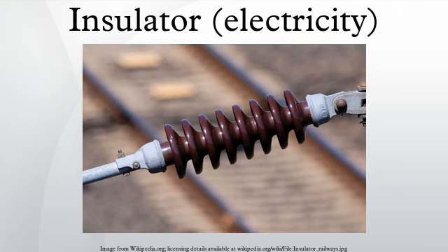However, wires that touch each other produce cross-connections, short circuits, and fire hazards. In coaxial cable, the center conductor must be supported exactly in the middle of the hollow shield in order to prevent wave reflections. Finally, wires that expose voltages higher than 60 V can cause human shock and electrocution hazards. Insulating coatings help to prevent all of these problems.